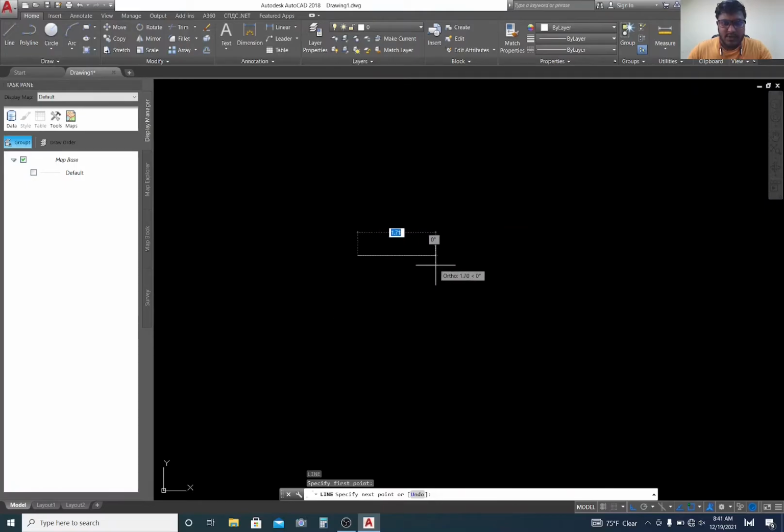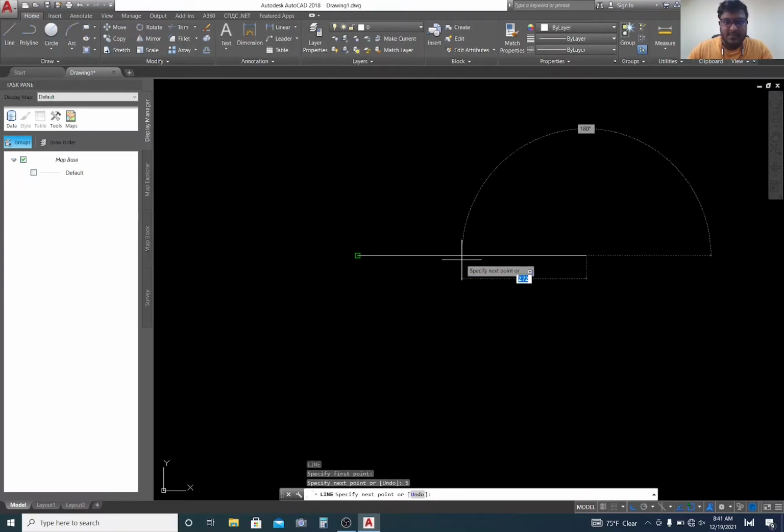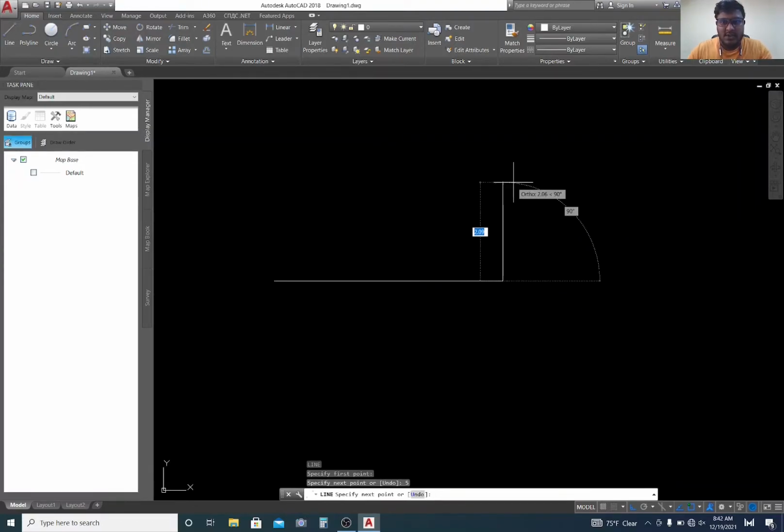Okay. So for that, we will make a rectangle now, 5 meter by 5 meter. It means length 5 meter. This will be the length, in the horizontal side. Now vertically we have to make 5 meter. So we already made our first edge. Again 5. If you type 5, it is equal to 5 meter.